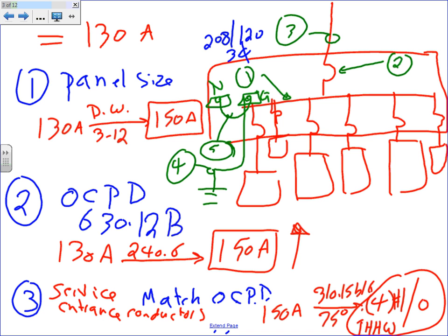So what I would like to do, guys, always is to put 2 inch PVC schedule 80 right at the top. That's what the feeder is. A feeder is nothing if you don't specify the conduit that these conductors are going to be housed in, right? So why PVC schedule 80? Good idea if you're doing 3-phase service underground, most likely. You're coming from underground. So put a 2 inch PVC schedule 80, 4 conductors, 1 AWG. Either you use your calculator or you can do it from, in this case, Annex C. Any questions, guys, about this?